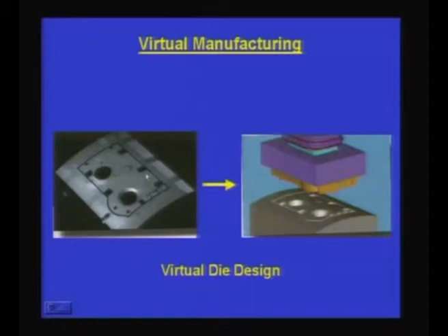This is actually a real part which one has to produce, for which you have already come up with a die shape. Now, I am carrying out a virtual forming operation, and I can look at the part which comes and compare it with the desired part, whether it meets the geometry and tolerances. If I have a problem, then I can correct the die shape, because of spring back or some other reasons.